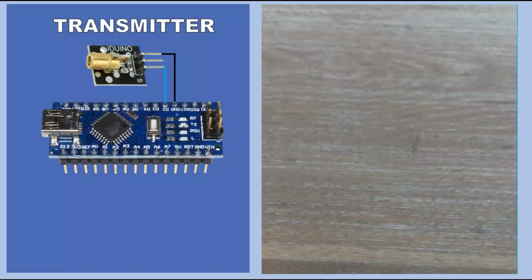I'm not going to show you this part of the project in detail because the code is just way too complex, and also with OLEDs I ran into the memory problem on a receiver part of the project. Basically, OLED display allocates 1K of RAM to buffer its activity, and together with the memory needed by my sketch, the measly 2 kilobytes of RAM provided by Arduino Nano got exhausted. I managed to fix it. The whole ordeal actually calls for entirely separate video. I just need to find time to make it.